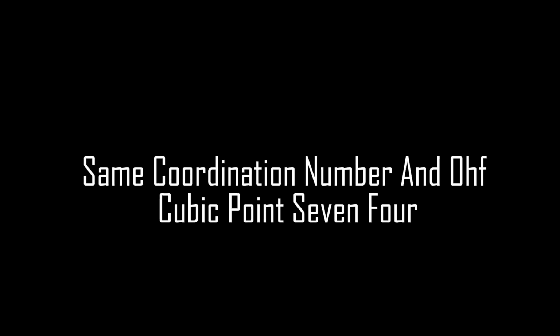Right, found in metals like magnesium, titanium, zinc, cadmium. Table 3.1 lists them. HCP is actually just as efficient at packing as FCC. Same coordination number, 12, and APF, 0.74. It's just a different stacking sequence of those close-packed layers. Gives it hexagonal symmetry instead of cubic.